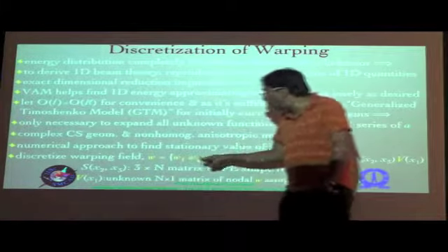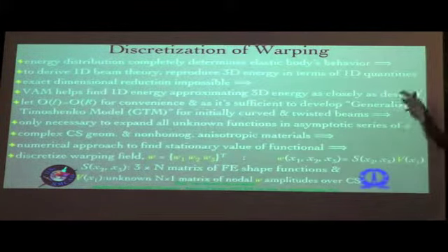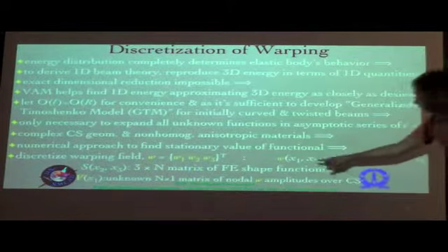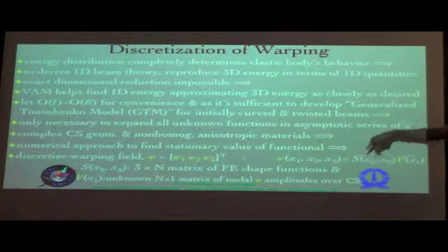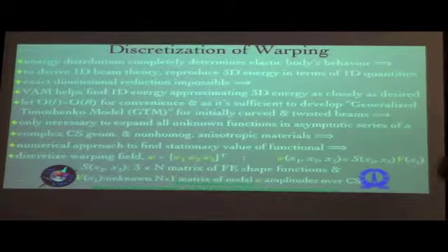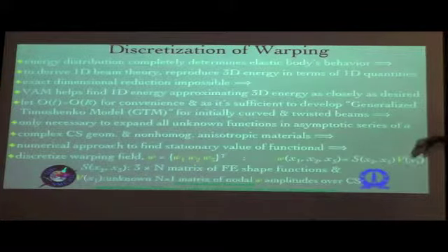So you have W equal to W1, W2, W3, a column vector, and that W we are now discretizing just like we do in any finite element implementation, by introducing shape functions for the x2 and x3 directions and basically the amplitudes. The amplitudes would now still be functions of x1 because we are dealing with only one particular cross section at a time.